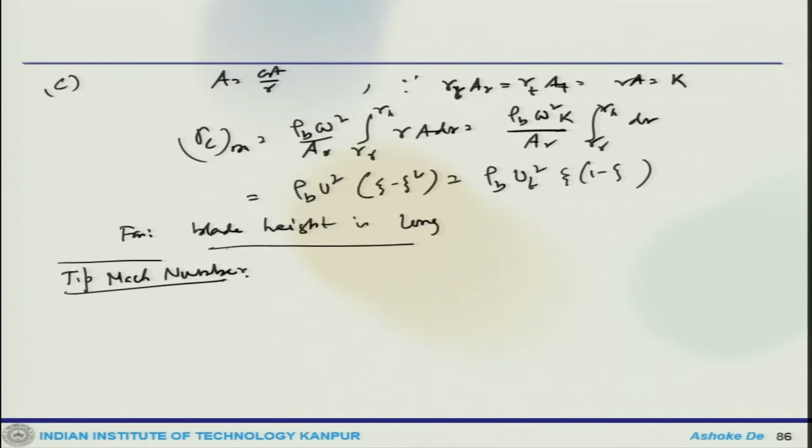Okay. So, let us look at these factors which actually cause this design of the axial flow compressor. We have looked at how the different basic design parameters like rotational speed and blade, and the kind of forces they are exposed to. So, we are looking at now the tip Mach number. This is another important parameter, because the maximum Mach number in the axial flow compressor occurs at the blade tip of the rotor inlet on the first stage. So, this is essentially maximum at